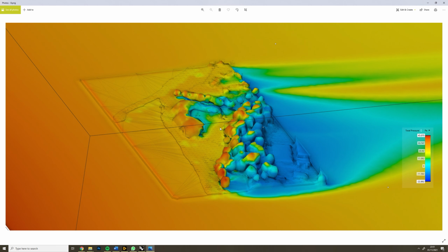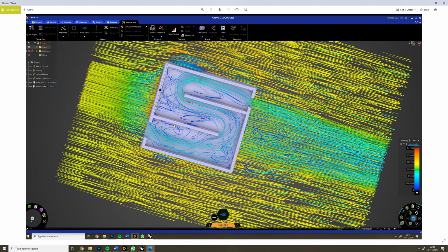We can also look at the wind load, or the pressure at which the wind will be applying onto the facade. So if a facade is considerably higher with pressure, it may be difficult to open doors, or it may force itself into the building, forcing natural ventilation. And if you want to model the interior, you can also test out natural or mechanical ventilation.